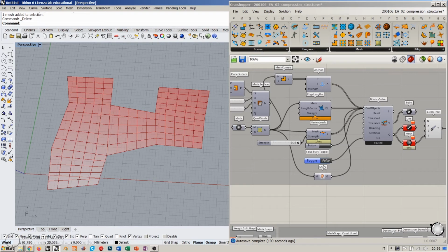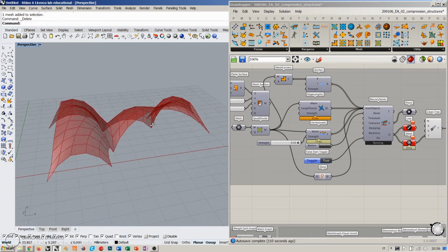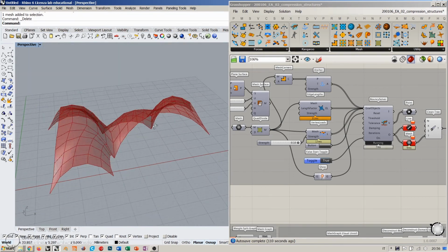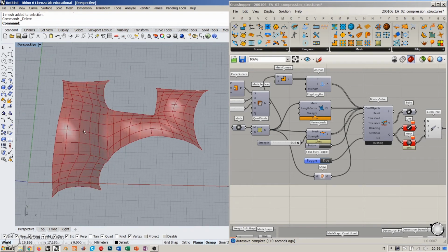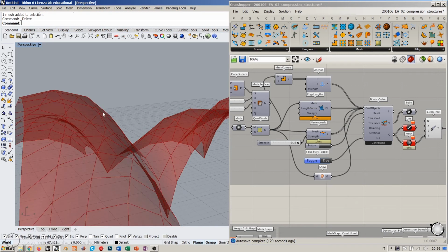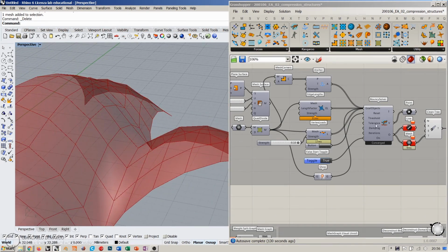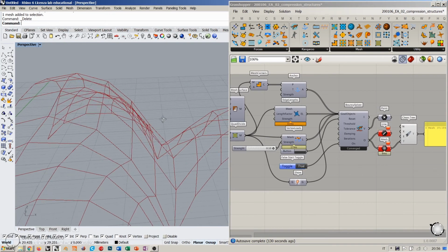But when you apply gravity to this object, and this object starts to fall down, well, up, or deform in general, there is no guarantee that these quads remain flat. Okay, so in order for these quads to remain flat, the only possibility is that the 4 vertices lie on the same plane. Okay, but this is basically impossible. So if you take a look at any of these polygons here, let me switch to wireframe preview.